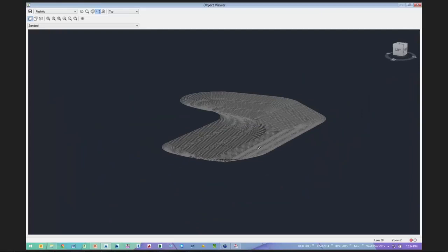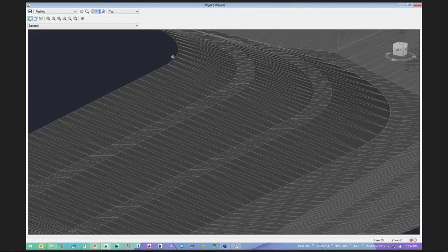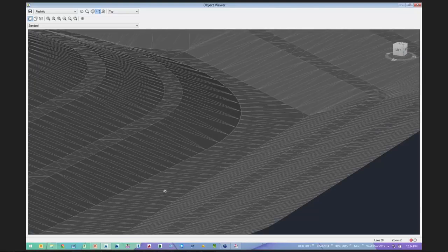Even though we didn't see any contours show up, you've got to make sure to put that infill in there. If that's not in there and you go to calculate your volumes, it's going to miss that entire section. So that entire area extruded up to the pond top surface, that volume will not be calculated. And you'll end up over-designing your pond.